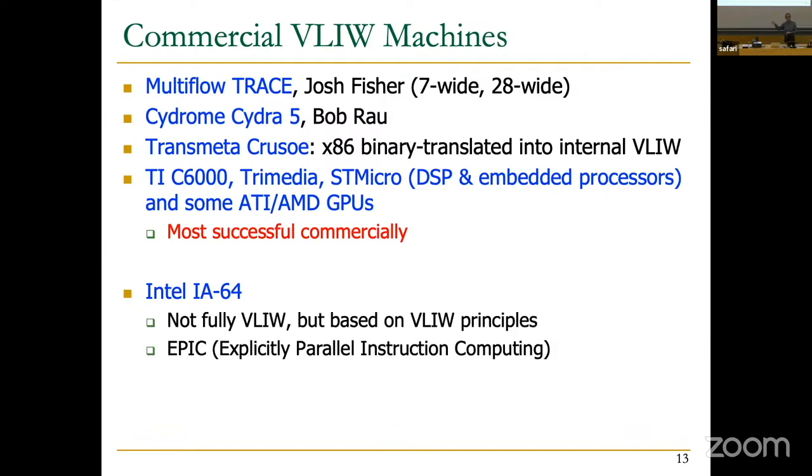It breaks some fundamental VLIW principles, meaning the instructions that are in a bundle, there could be dependencies there. But the compiler tells which instructions are dependent, such that the hardware's job is easier. So this is a kind of mixed model where the compiler doesn't fully guarantee independence, but when it cannot guarantee independence, it tells the hardware, oh, these instructions are dependent or may be dependent on each other.